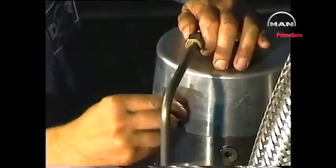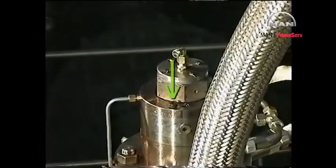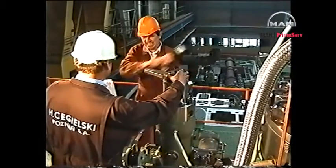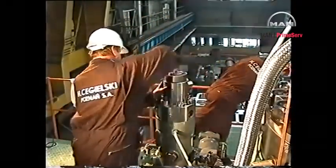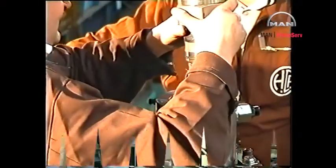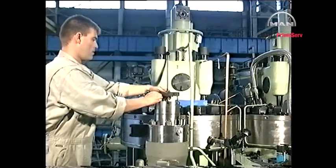Disconnect the air pipe and remove the cover from the puncture valve. Remove the plug screws to provide access for the measuring tool. Remove the puncture valve. Mount the measuring tool, making sure that it engages correctly with the bore in the top of the fuel pump plunger.